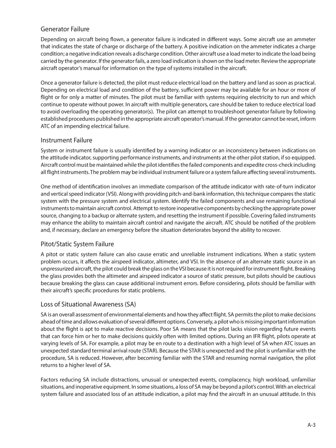Loss of situational awareness, SA. SA is an overall assessment of environmental elements and how they affect flight. SA permits the pilot to make decisions ahead of time and allows evaluation of several different options. Conversely, a pilot who is missing important information about the flight is apt to make reactive decisions. Poor SA means that the pilot lacks vision regarding future events that can force him or her to make decisions quickly, often with limited options.